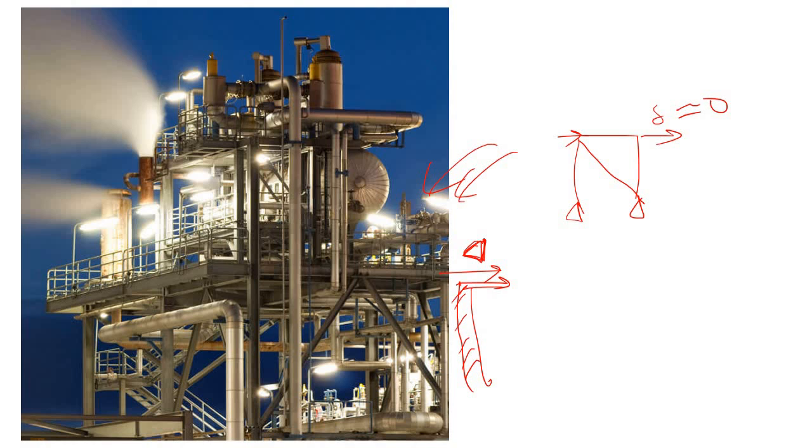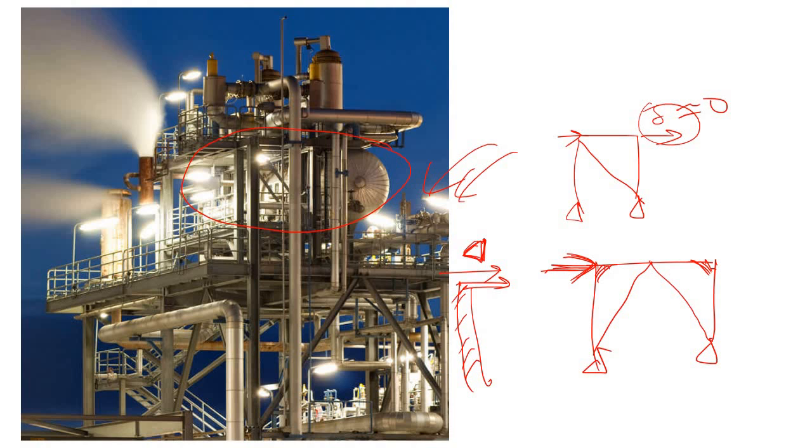Okay, so to carry this exchanger, maybe your moment connection is sufficient to carry the lateral load that is coming due to the bundle pull extraction. But to minimize the lateral drift, I prefer that we at least provide a bracing like this.